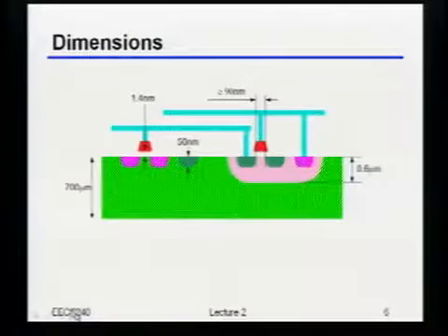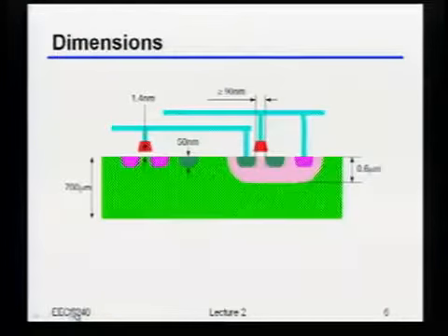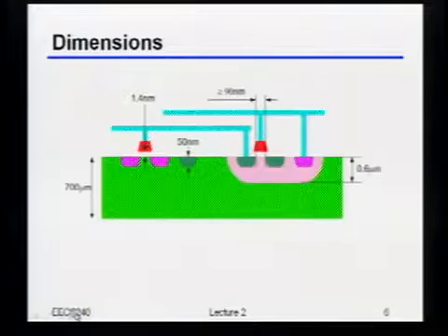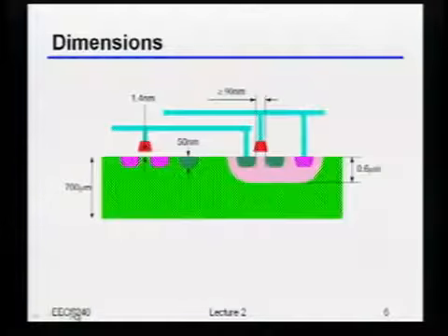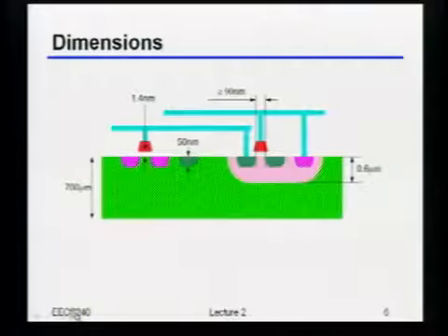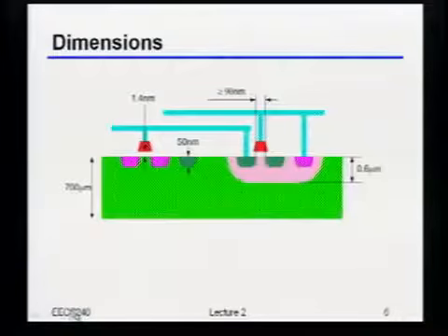But actually, that's turning out to be a more interesting relationship these days, because now people are even talking about transistors where rather than the effective length being shorter, actually it's longer. So if you look at like a 22 nanometer process, people are talking about effective channel lengths of 23 or 24. Okay, if you're interested in why, come bug me, I'll explain it, but just keep in mind, process technology does not necessarily mean effective channel length of the device. Okay?